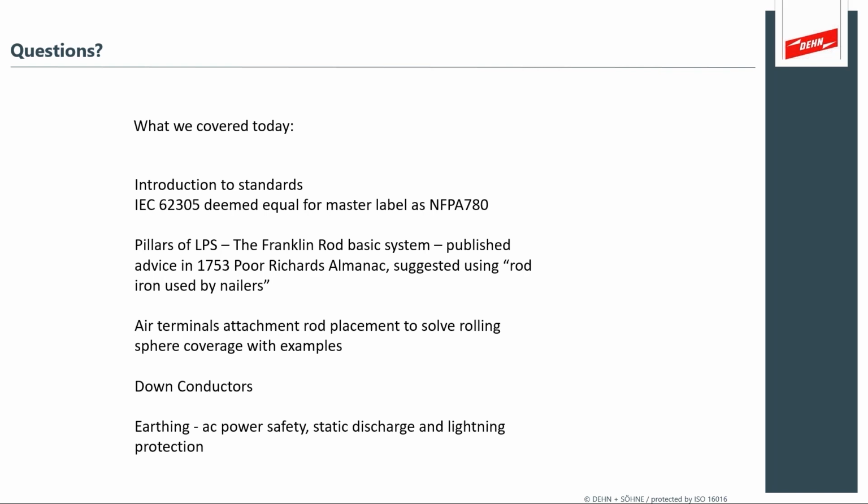The other portion of HVAC is that it's inevitably going to lead back to some very valuable air handler, chiller system, and control system. So you're putting the lightning currents directly into the structure where you may not want them diverted. And then you have to pay attention to every single joint through that HVAC system.